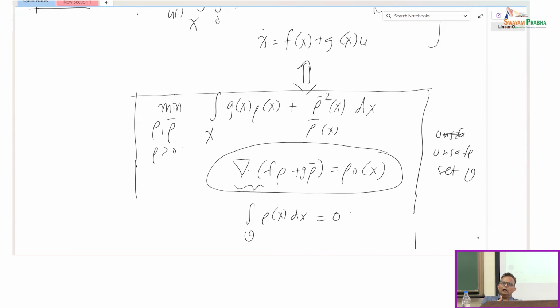Now, instead of creating the attracting and repelling potentials, or a combination of attracting and repelling potentials using a navigation function, you can construct density-based functions, which are based on occupancy. What you can say is that, I want to avoid this set, so I will make my density 0 on that set. Because if the density is 0, I'm not going to get there. And I want to get to the target set, so I will make the density very large there, because that's where I want my mass to eventually accumulate. Everything goes there.